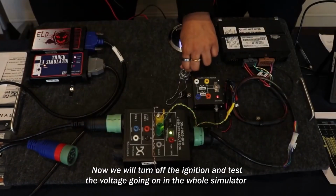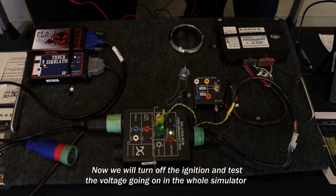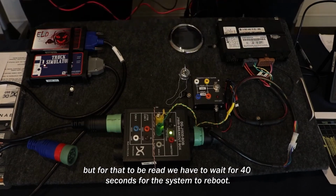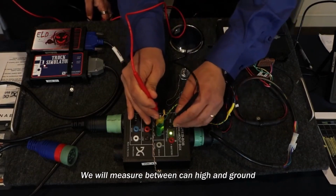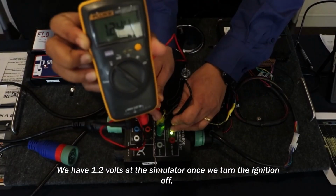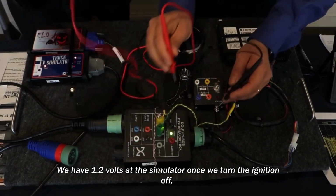Now we will turn off the ignition and test the voltage in the whole simulator. But for that to be read, we have to wait 40 seconds for the system to reboot. We will measure between CAN high and the ground. We have 1.2 volts at the simulator once we turn the ignition off.